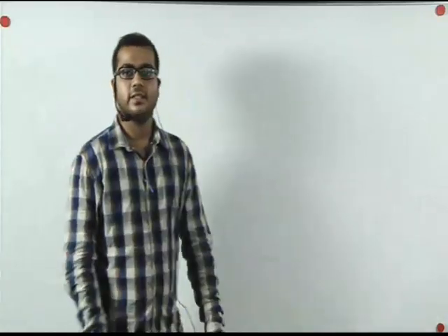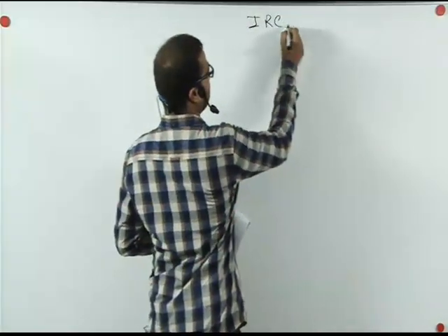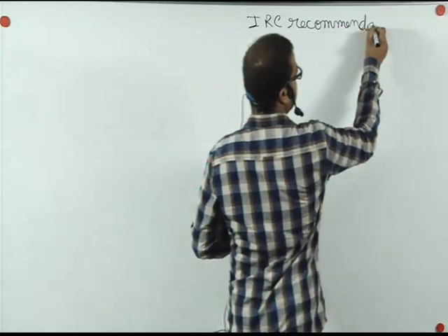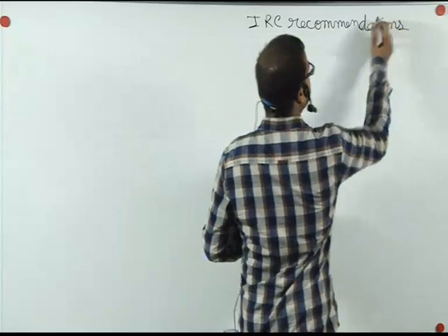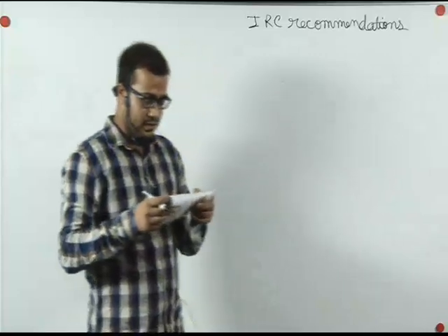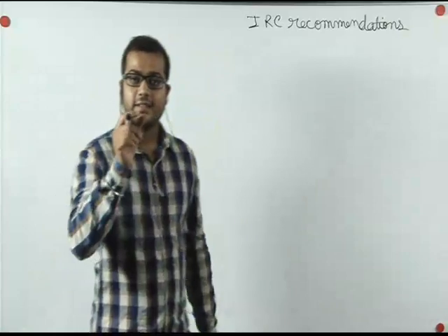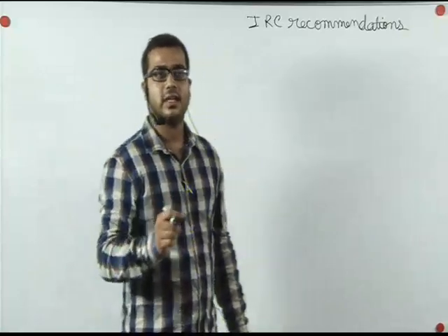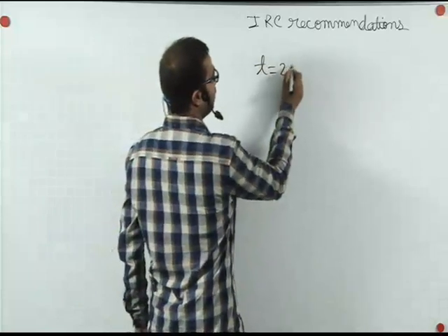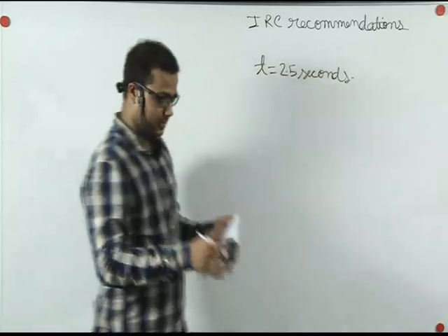As per IRC, Indian Roads Congress recommendations, when we find the braking distance, we require the reaction time, and that reaction time of a driver is considered as 2.5 seconds. Generally, the reaction time is considered as 2.5 seconds as per IRC recommendations.